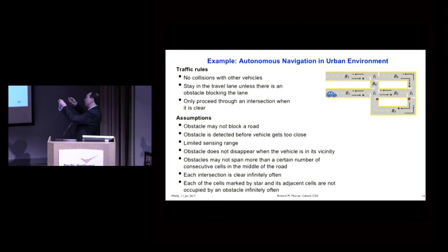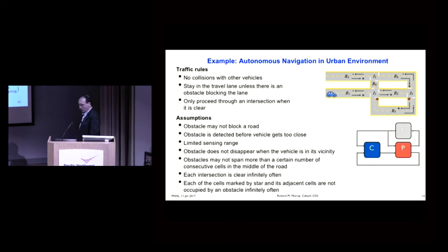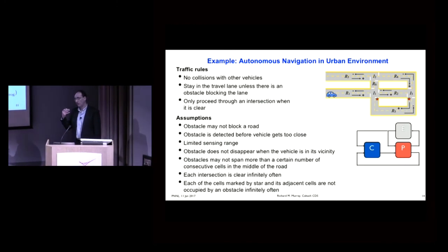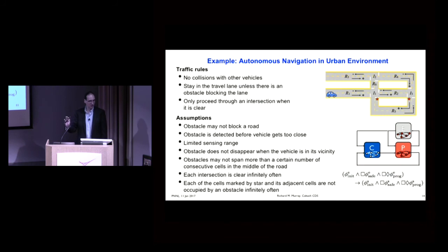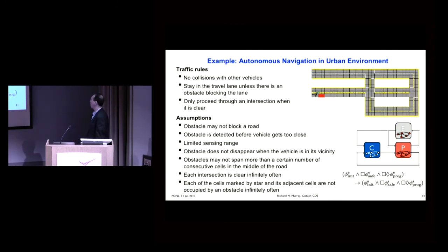Okay, so it turns out everything I've written here and the many pages that are behind it can all be described as exactly this type of system where we have finite state automata, we have a GR1 specification, and we solve it. And I'll show you what the solution to that looks like. So I'm going to show you an animation, and what I want to tell you about this animation is that the logic and the trajectories that the car is following in this animation, it's obviously a model, were completely synthesized. We did not do any design. We just gave it the specification. And we gave it the system model, you know, here's what it means to drive on the road and turn your wheel and all those things, and then it synthesized both the continuous controller as well as the discrete controller to do this.